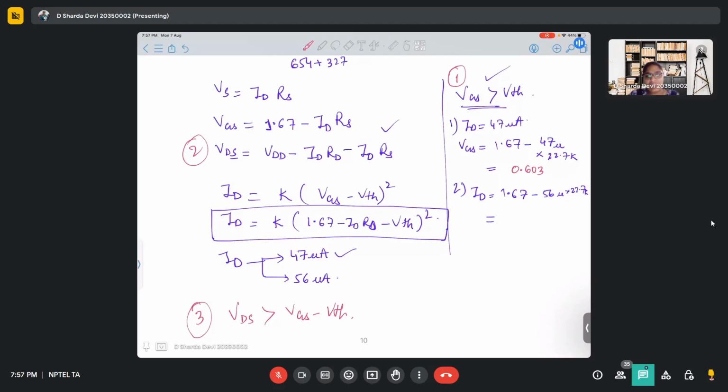First of all, the basic condition that we should always check is whether the transistor is on or not. That is the very first condition, like VGS greater than VTH. Because sometimes your VDS condition is satisfied, like in a few questions I have come across, but the VGS greater than VTH condition doesn't satisfy. And it confuses people: the VDS condition is satisfied, so why is the question wrong?